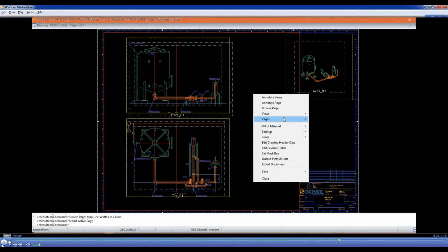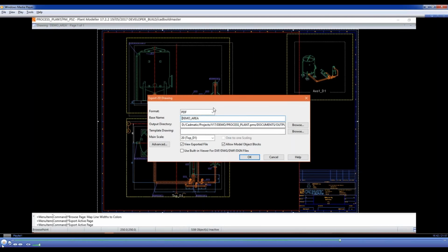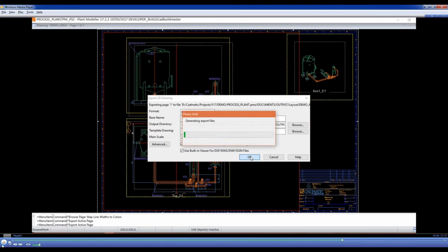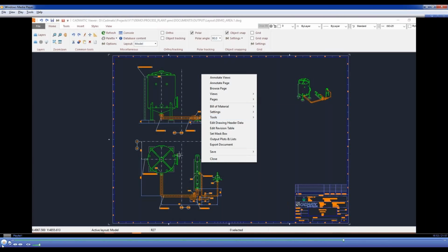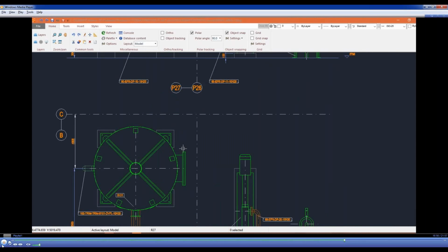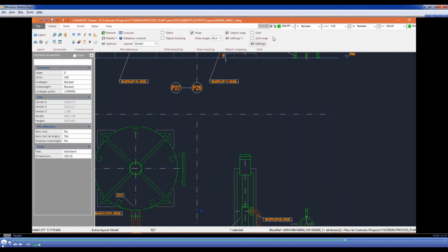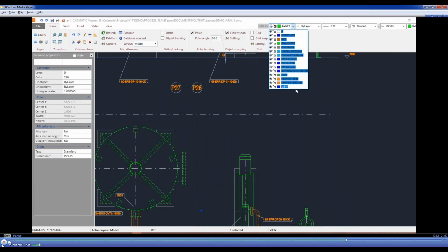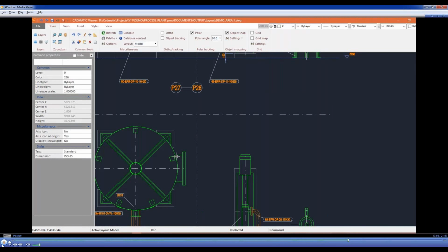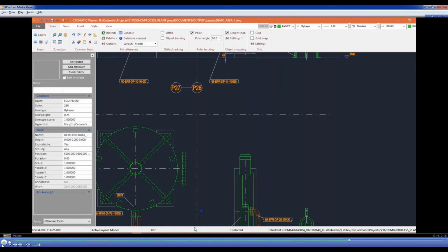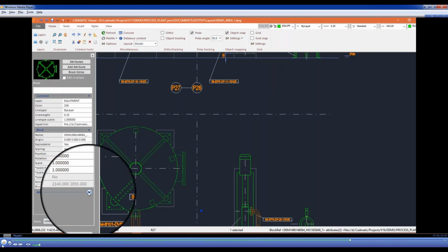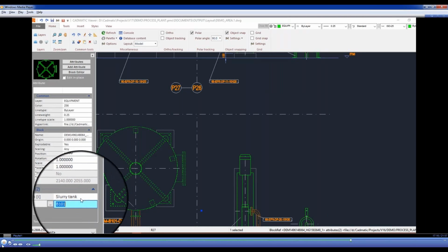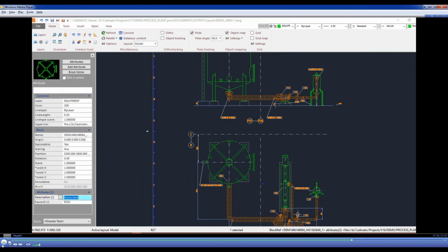Then next I will export to DWG. Here are also other formats that you can use, and I will use this our build viewer so that you can see immediately what it is. No need for other licenses. Here, if you check the equipment, we have this layer available and all other layers in the drawing. And also, if you query properties of this tank, you can find some attributes which are already filled at the diagram actually.